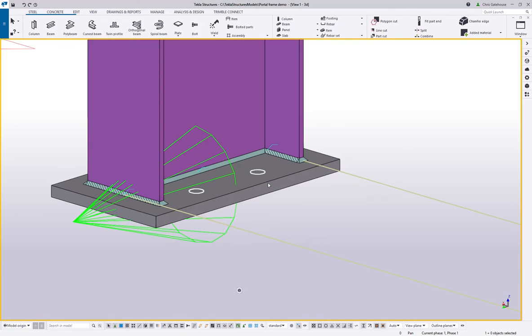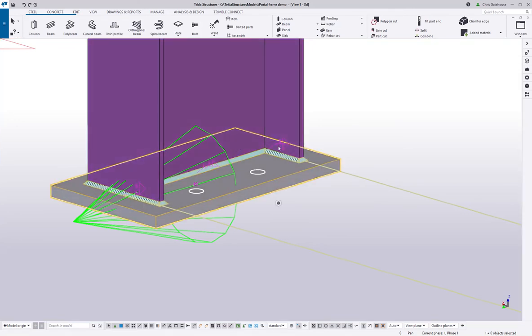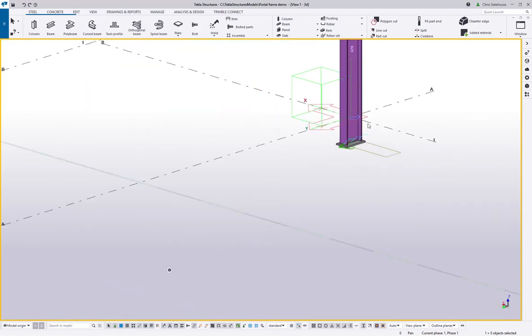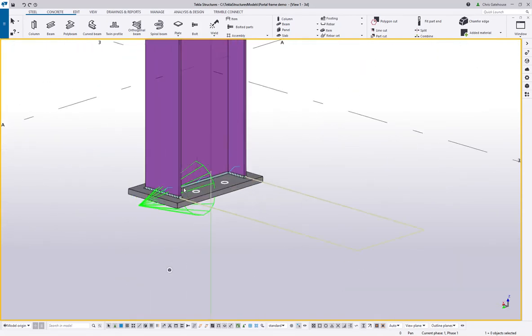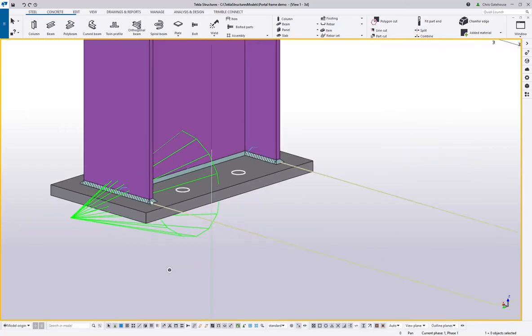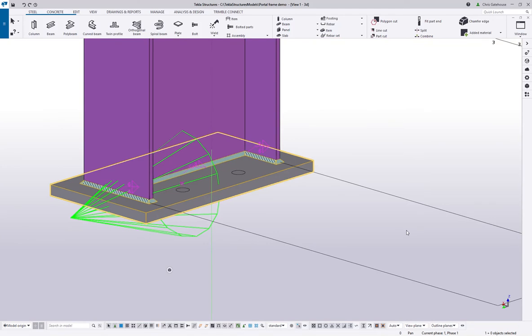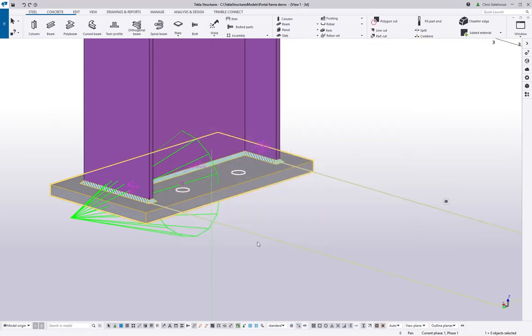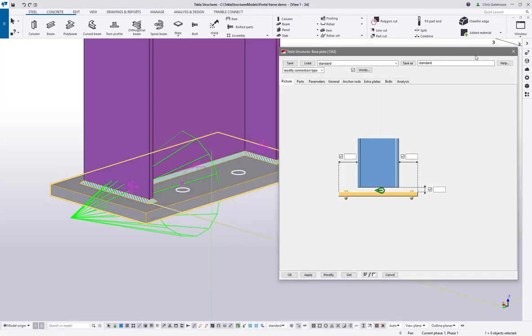You'll note that selecting the component object highlights the weld specification as well. And this green top hat here is indicating that a component exists. Okay, so that's sort of suggesting the intelligence exists. Once I've set a component and I apply it, that means that setting is stored. So every component that I create from this point forward uses those settings. We can also double click on that to bring up this window and change it as well.